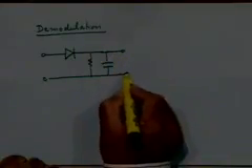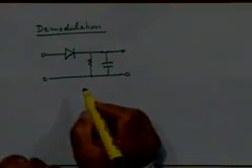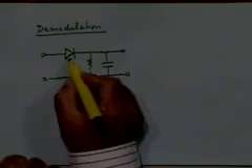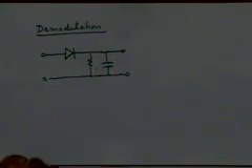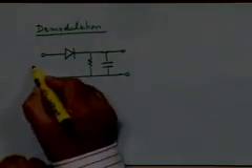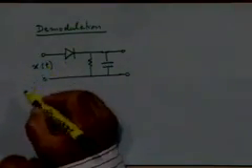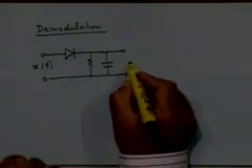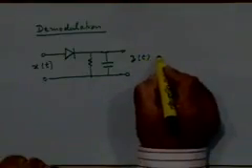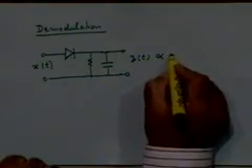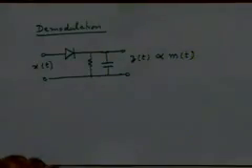And what could be simpler than this? Right? You have a diode, you have a suitable value of the resistor here and a suitable value of the capacitor here. Input is your modulated waveform x(t) and output is, let's say, z(t), which is, we will soon see, proportional to the message signal m(t). Okay.